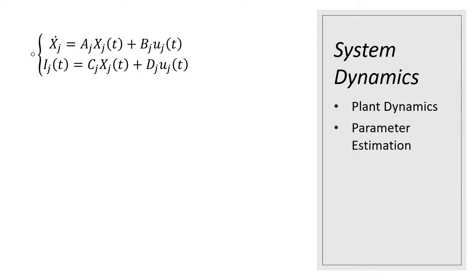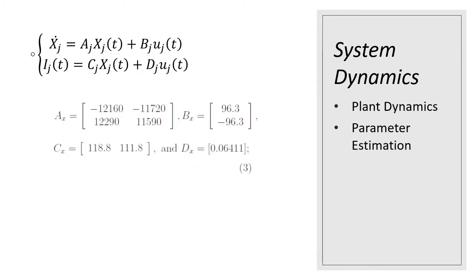Now, unfortunately, modeling the system parameters cannot be done directly. So what the authors did is to consider two sinusoidal inputs and measure the corresponding output currents, and then do a curve fitting. For the three axes of the Helmholtz coils, they found the following matrices.